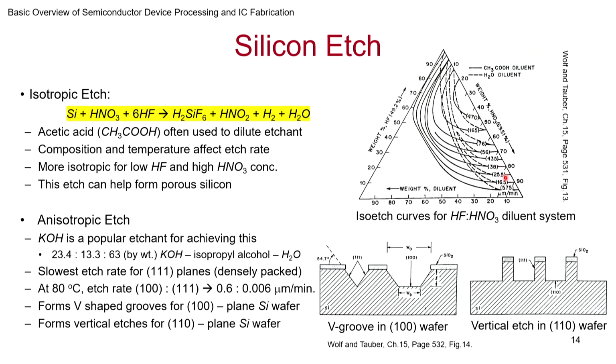So what do you find? You find that as it starts etching, the 111 planes get exposed. This is where you can sometimes make use of it, and as I said, in areas like MEMS and other places, you can make use of these structures for getting a diaphragm and so on. The slowest etch rate being that. So if you use a 100 wafer, the 111 planes will be like this. So you end up getting V grooves. In fact, this same technique could also be used for solar cells when you want pyramid-like structures on the top. But remember that it has to be a 100 wafer.